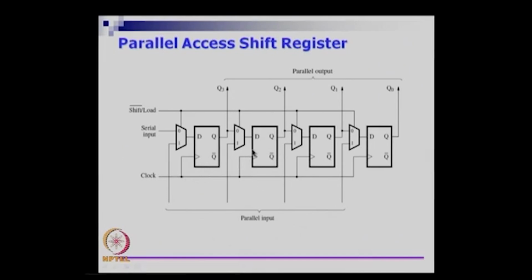It seems to take the same clock input to everything, which means it is a synchronous circuit, and you are seeing that there are 4 lines coming out and 4 lines coming in. So it seems to have something coming in parallel, and something going out in parallel. This part of it resembles just a register.